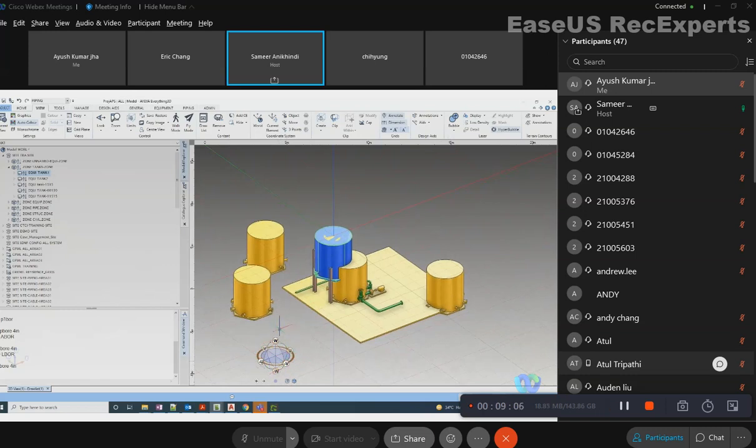And you can see the coordinate system also changes. Instead of using E, N and U for elevation, it is showing UVW. W is elevation, U is easting, and V is northing. So this is how it happens because it is not right to call it E and U. So the labels are changed. You can switch back to world coordinate system anytime by pressing this.